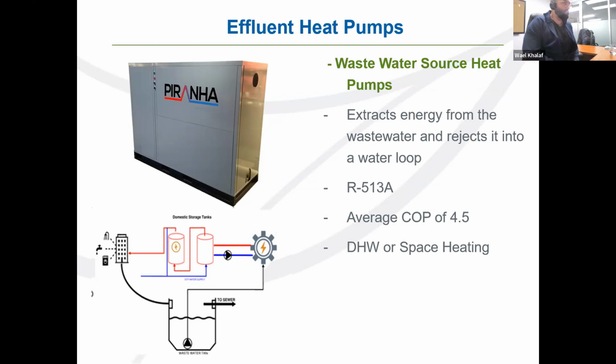So the residential side of things is a great potential for this, where you have a couple of peaks during the day. In the morning, everybody's going to go take their showers, so you're seeing a significant inrush of warm temperature water going down the drain. So if you can tap into that main combined sewer for your building, you run that water through this heat pump, you cool it down, and through the refrigeration cycle, you'll be able to take that energy, decouple it, and reuse it to preheat your domestic hot water, or not only to preheat, but to provide all the domestic hot water production you need for a particular building. So it can be very small.